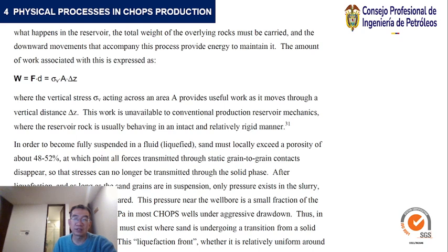This pressure near the wellbore is a small fraction of the overburden stress, less than 1 MPa in most CHOPS wells under aggressive drawdown. Thus, in the medium, a liquefaction front must exist where sand is undergoing a transition from a solid condition to a slurry condition.